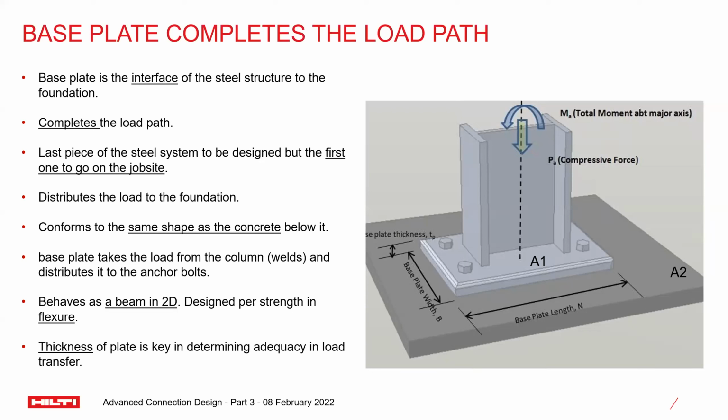This is also evident from both Eurocode and American codes, which include the area calculations of both the base plate itself and the concrete, and then you make a simple calculation out of it to understand the stress that you're putting onto your main material, which is the concrete. And just imagine what would happen in the absence of base plates. We would be transferring point loads into the concrete, which depending on the magnitude could cause a punching effect and damage the concrete, right?